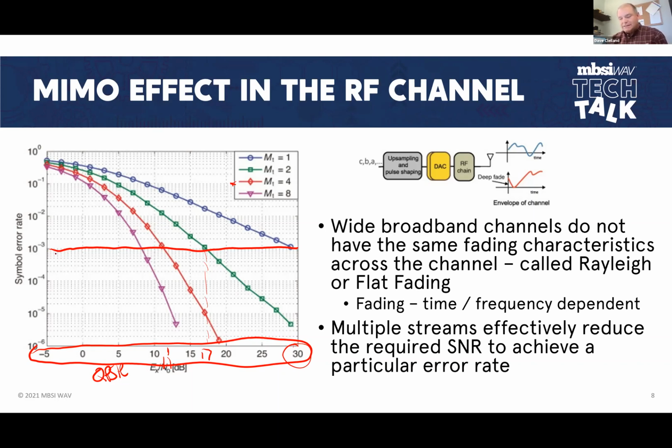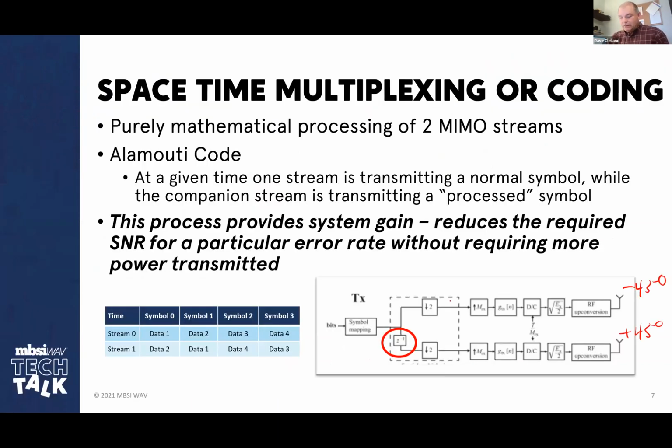Also, you can see through all of this that if you have half of the MIMO chain not working, let's say, for example, you've got an antenna jumper that goes bad. So the left slant is working okay, but the right slant has high reflected power, high attenuation, and it's not working right. Well, we go back to the receiver, which may or may not be able to handle that. Let me go back to one more.